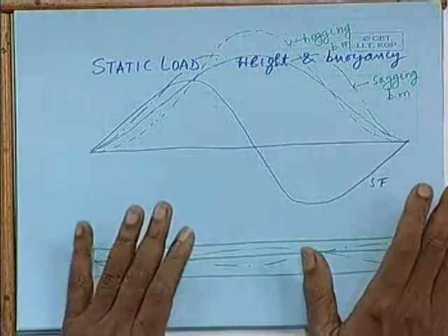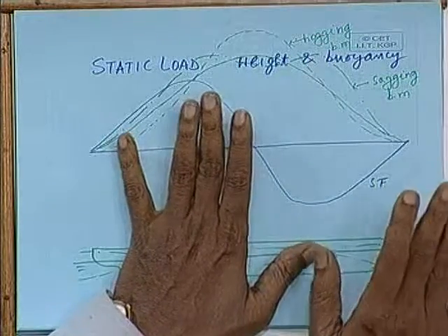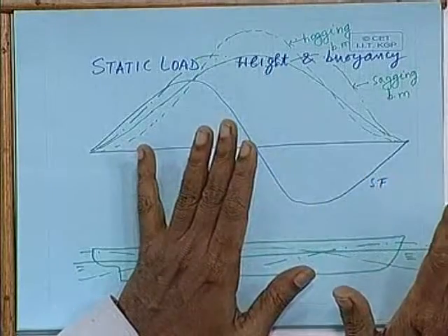Can you see that? So, this is without taking any dynamic effects. The static load that we calculated, we can see, will vary depending on the wave orientation along the length of the ship. Now, when a ship goes in a seaway, of course, this is not what happens. You do not have a wave equal to the ship's wavelength and poised with either the crest or the trough in the middle. We normally have a sea, a random sea, where there are a number of crests of